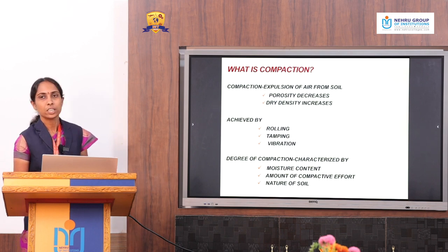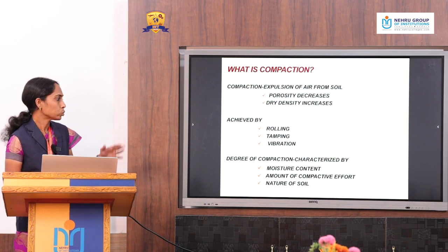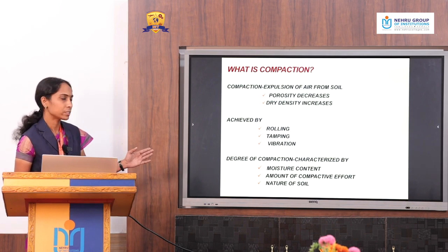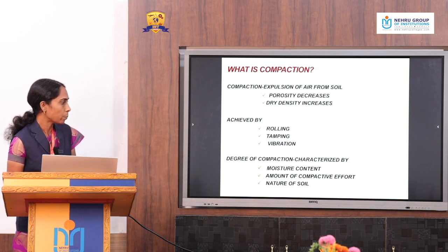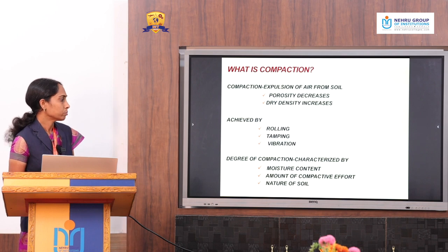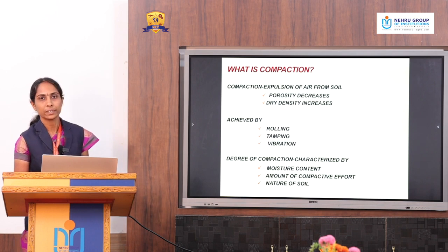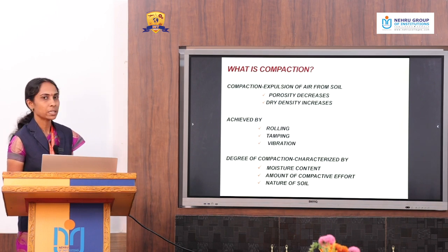And there is a degree of compaction. There may be a high degree of compaction and a low degree of compaction. The degree of compaction is characterized by three factors, that is the moisture content, the amount of compactive effort and the nature of the soil. That is the moisture content. If the moisture content increases, the degree of compaction varies.